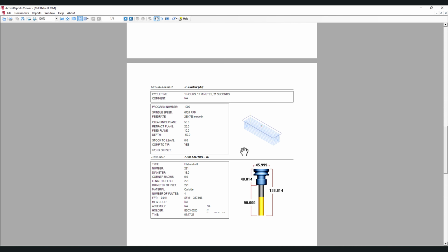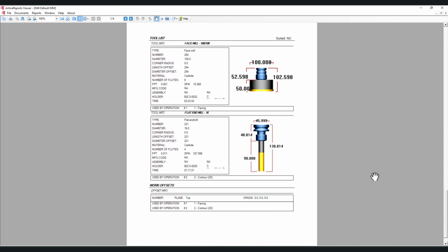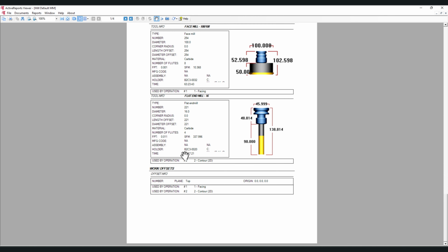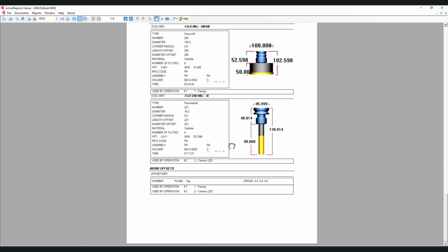And next is your contour profile, which is covered with your operations, and this is the tool list with more details and the holder code. If you want a different code also, you can manufacture it, or you can align as it is with your available tool holders. You can also create a Mastercam library and use it. And this is my work offset, which is my X0, Y0 and Z0. This will be my offset, but it will be based on the machine. It will vary because it is an education version. I have not put this.